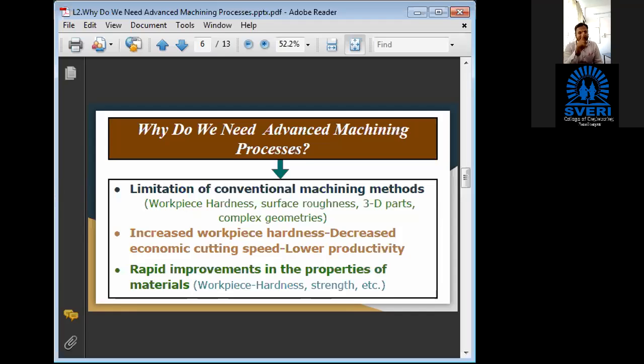That means your surface roughness value, in nanometers. Whatever the surface finish is, that is the surface roughness value, the Ra value it is called, and it is measured in nanometers. So they want it to be very low. Surface roughness value should be very low, which means surface finish should be at a very high level. Some industries are in demand of nano level surface finish.